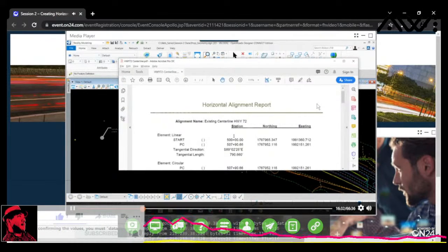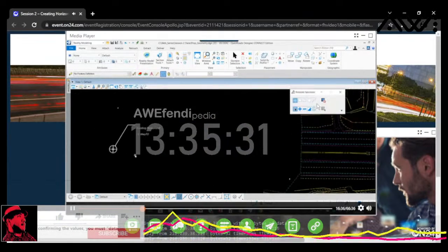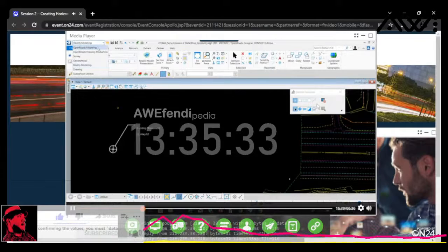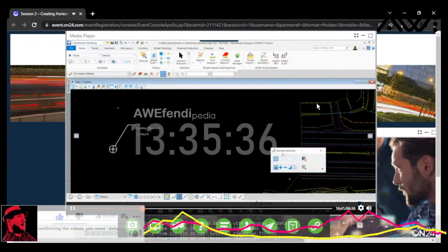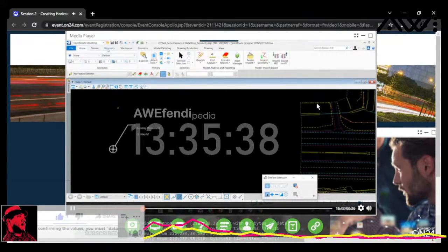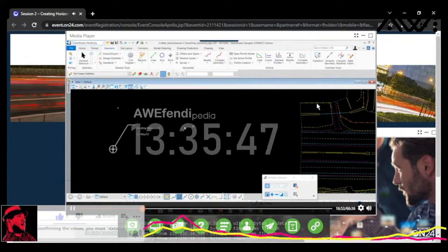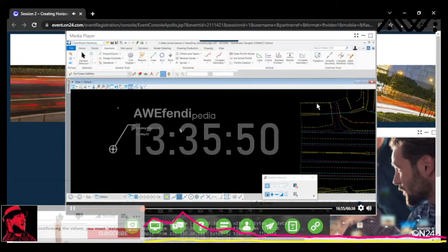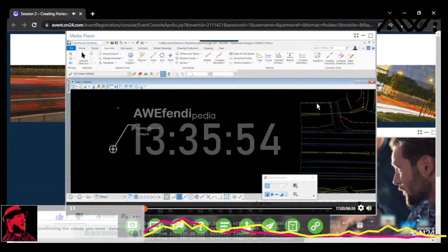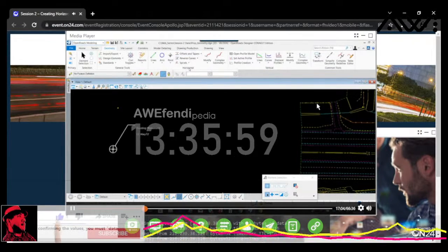Now, I'm going to start, and I'm going to lay this out first of all graphically. So I'm going to go to the OpenRoads Modeling workflow, go over to the Geometry tab, and again, I'm going to lay this out graphically by elements, meaning I'm going to draw tangents, I'm going to draw arcs, and so forth, and then put them all together in an alignment, adhering to that known bearing distance, curve radius, curve length, and so forth. So to begin, again, we're on the Geometry tab. We'll get on this area under the Geometry Tools, and we're going to begin by just placing a line.